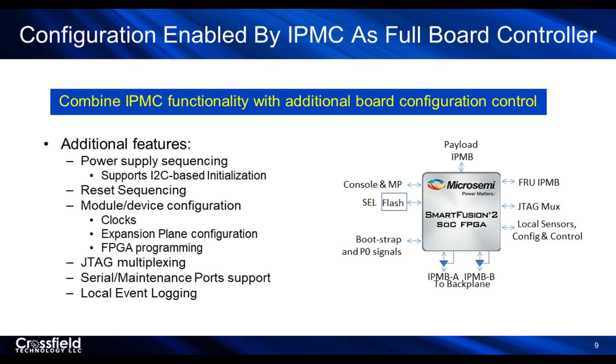The things I already talked about, right? The clocks, the expansion plane configuration. And what I haven't mentioned is FPGA programming. If you've got an FPGA on your card, which a lot of cards are going out the door today with FPGAs on them, you can give them completely different images that could be controlled by a board controller IPMC combination to provide totally different functionality.